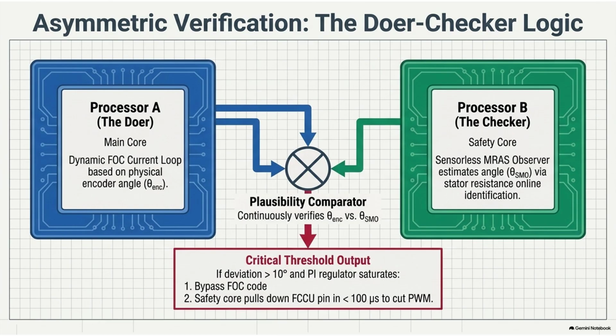Well, with the motor spinning over 7,200 RPM, switching to sensorless control might not be stable enough to manage the immense rotational energy. You also face the danger of the motor itself. I mean, a spinning electric motor is inherently a generator. Oh, exactly. If a catastrophic sensor failure occurs at high speed, you cannot just open the circuits and let the